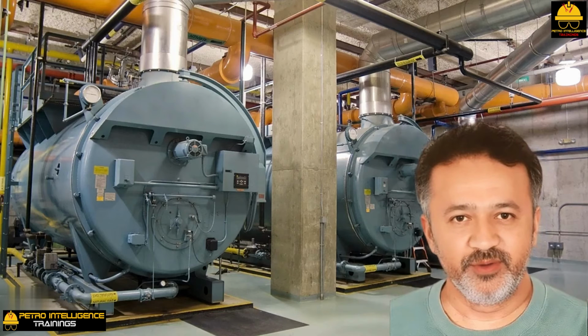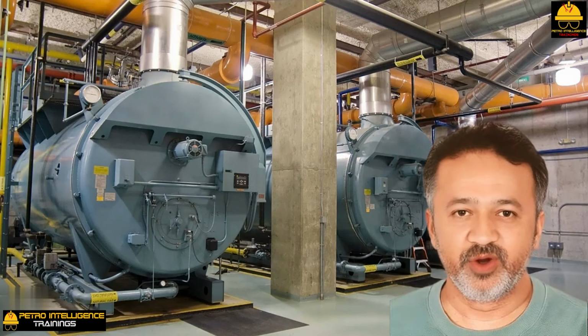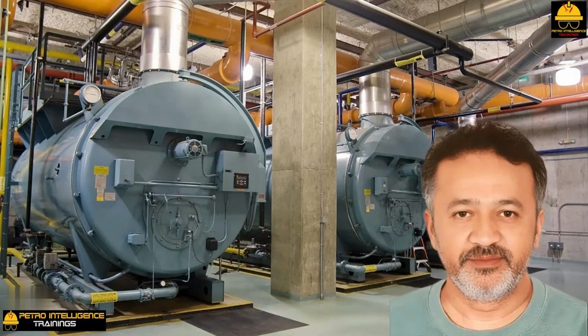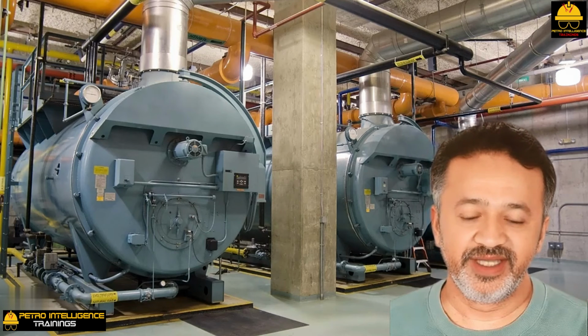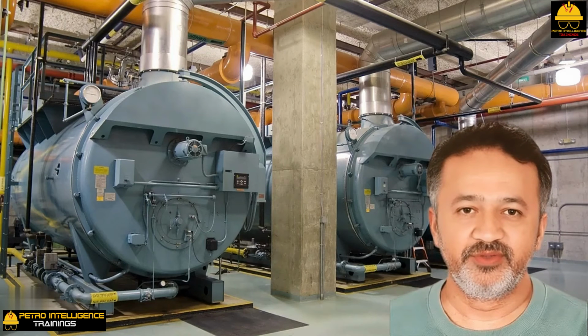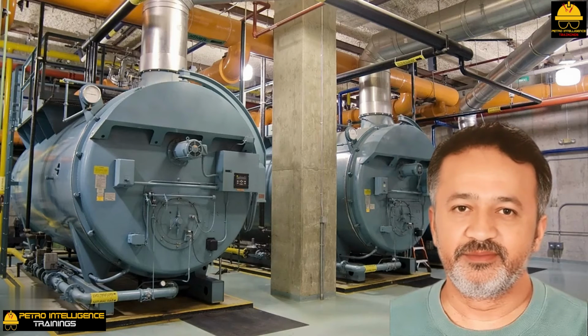The listeners will note that I emphasized the word "several," rather than stating a target O2 range in this example. There is no such range. The optimum O2 in the stack is whatever it is to maximize steam production. Which means the O2 analyzer served no function in the control of this boiler. And that statement is, in general, true.